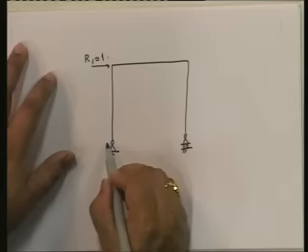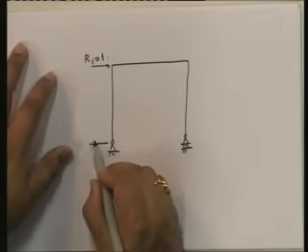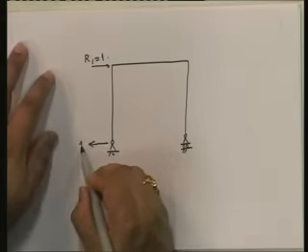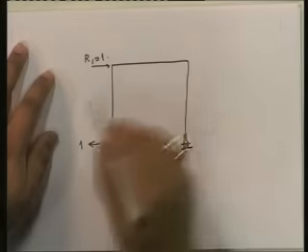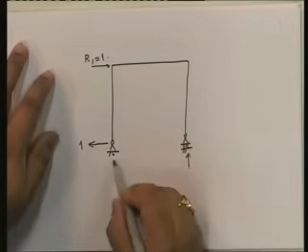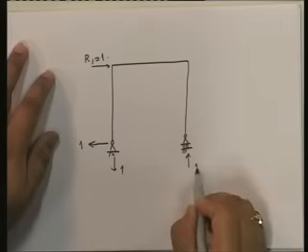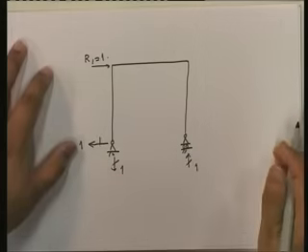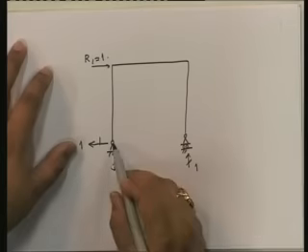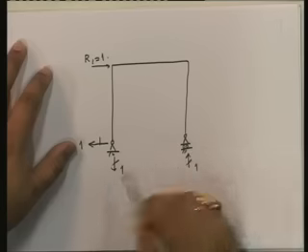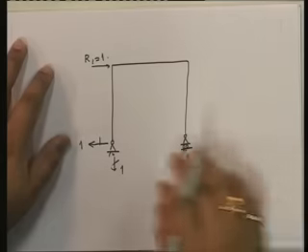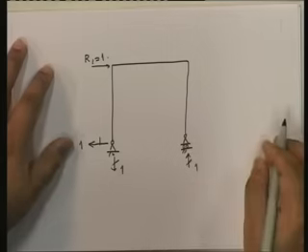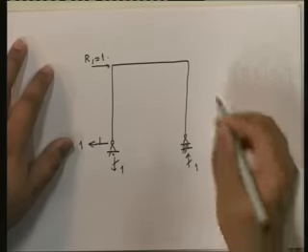If you look at this, you will see that this gives rise to 1. So the reactions: sigma Fx equal to 0, sigma M equal to 0 taking moments about this point, and then sigma Fy equal to 0 gives me all of these. And once I have all of these, my member end moments become this.